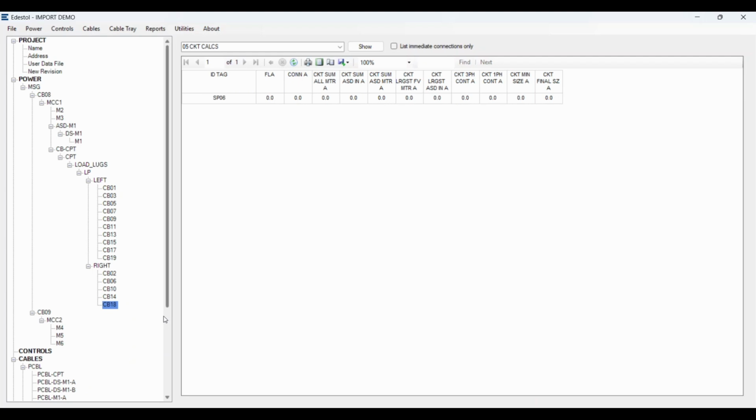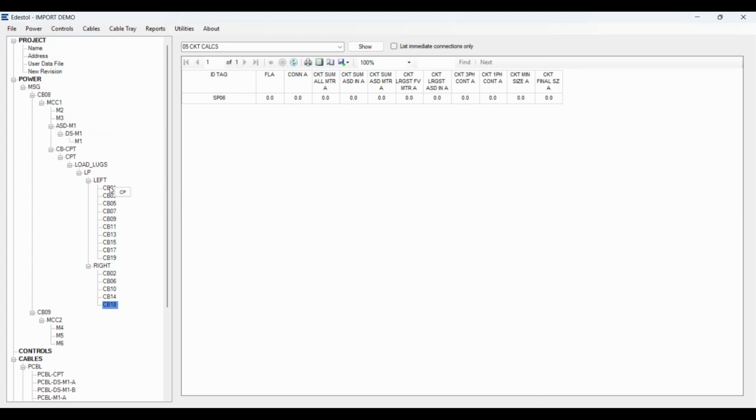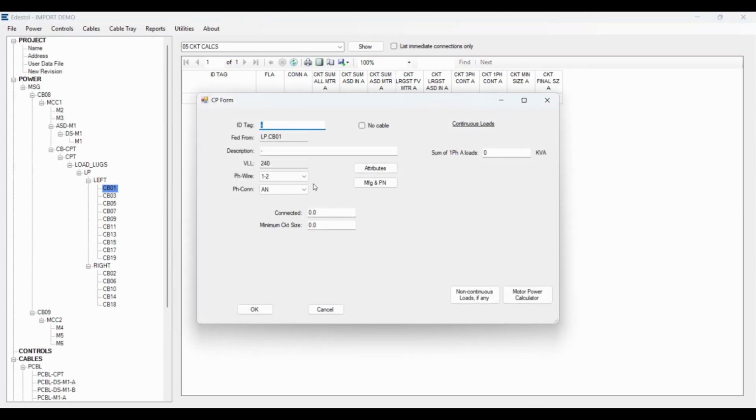In this case, what we're going to do is start at a PLC panel. So let's go ahead and take one of our loads, and we're going to go down here to a control panel, and we're going to drop that on our first 20 amp breaker. And we're going to label this PLC. Okay, this is our main PLC panel. And let's give it a size. Let's just say it's 750. So this is 0.75 because this is kVA amount. So we're just going to say 750 VA.